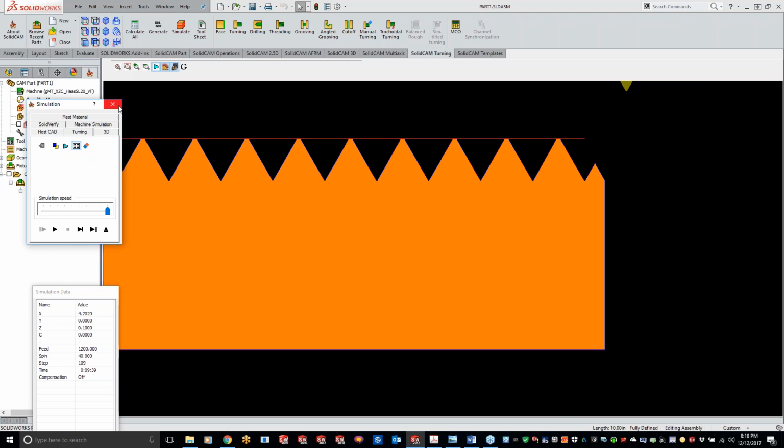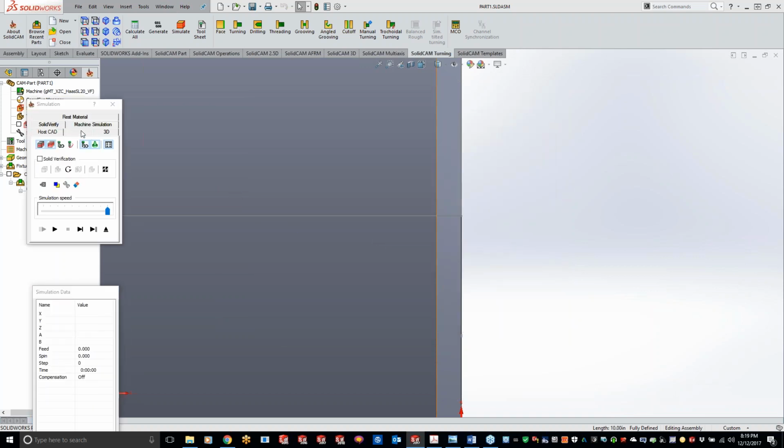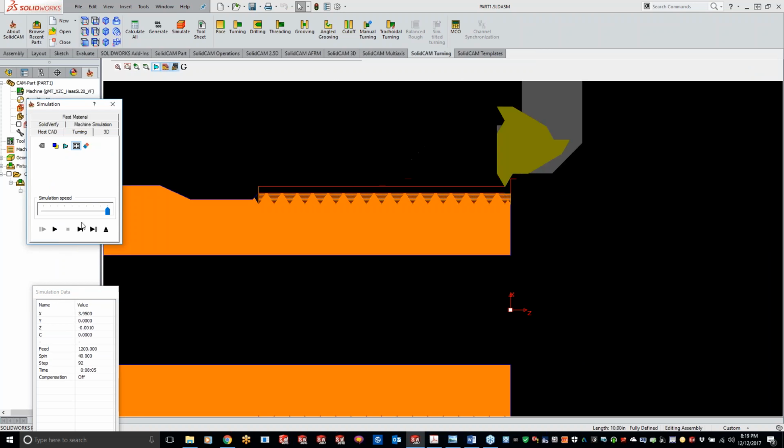Okay, so the one pass along the top is going to be this one right here. Is this what you're looking for? Okay, perfect. Sorry about that, Ben. So this is going to clean off your tops, going one pass above. Let's turn that on, save and calculate, simulate it, turning here. I'll try to pause it and slow it down for you. There we go. So it's just cleaning off the tips going along.